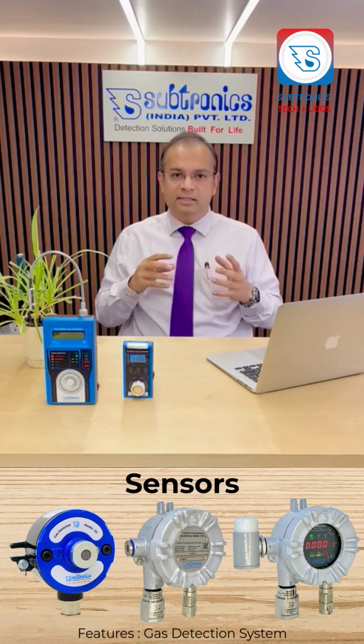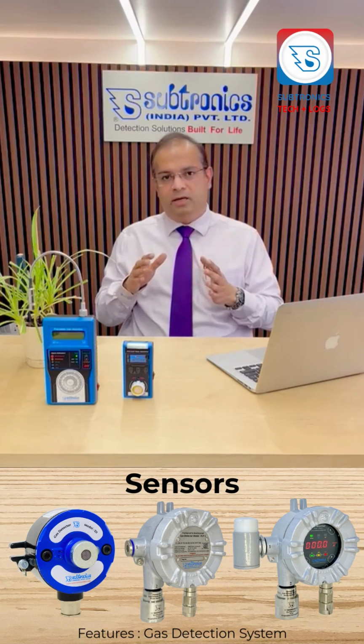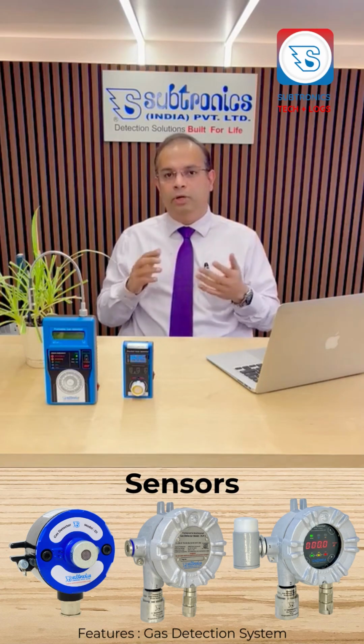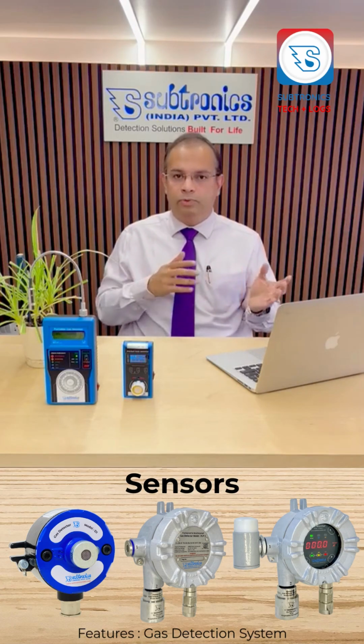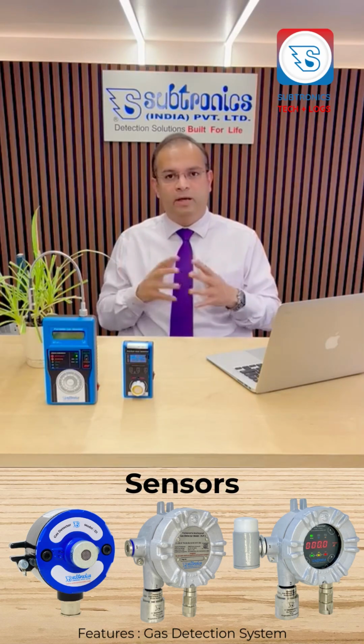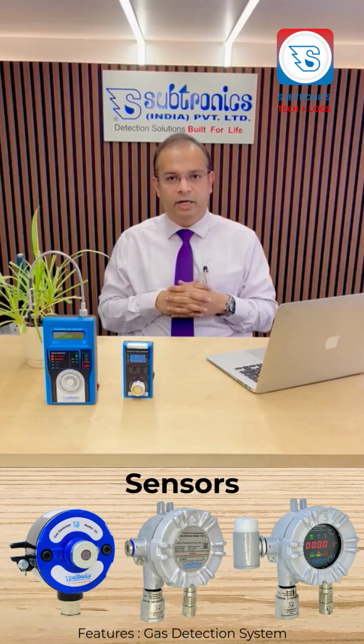Now these sensors have typical features like a 0 to 5 volt or 0 to 2 volt output, or a 4 to 20 milliampere output, or a Modbus output which goes further to the control unit. It depends on the make and the type of panels. We have a lot of panels to which you can interface these detectors.